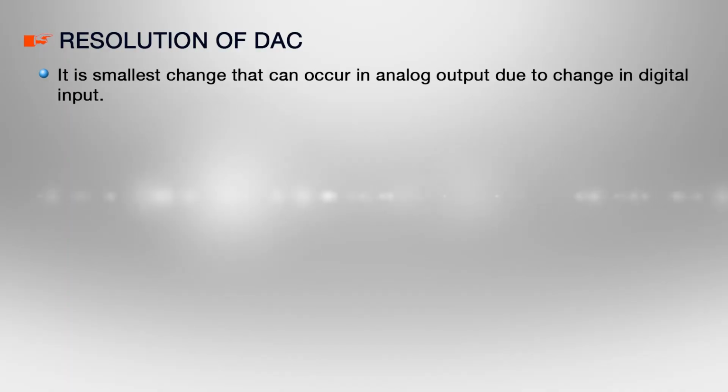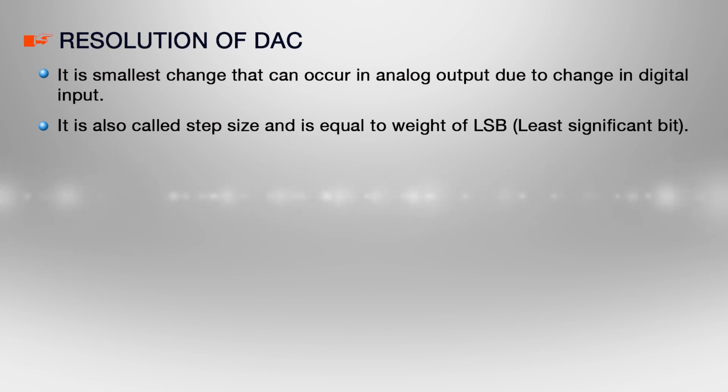Resolution is a very important performance characteristic of DAC. Resolution is defined as the smallest change that can occur in analog output due to a change in digital input. It is also called step size and is equal to the weight of the LSB, that is, the least significant bit.